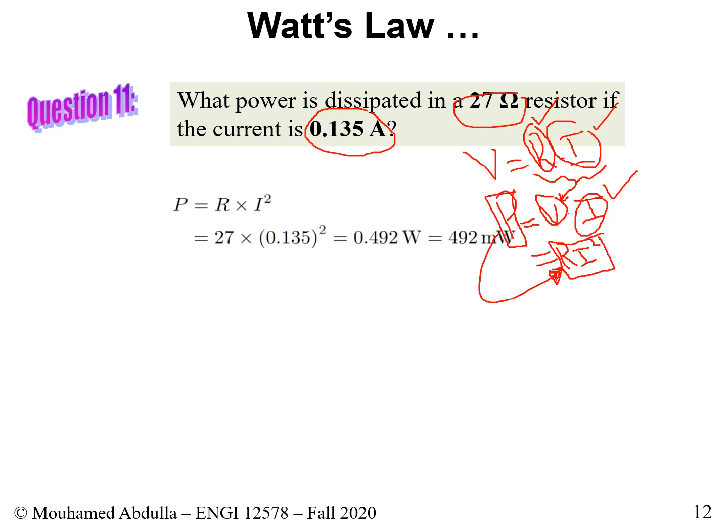So anyways, let's just do it. Let's say we know it in this case. P is equal to R times I squared. The resistance is 27, the current is this, we multiply through, we get 0.492 watts. We represent it in engineering notation, we move by 3 digits to the right, it becomes 492 milliwatt, and now we could simply write the answer. This is it, 492 milliwatt.